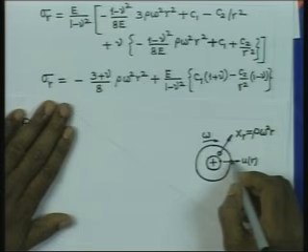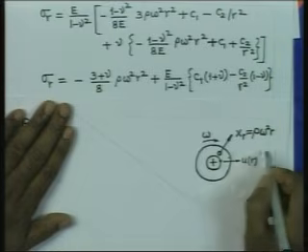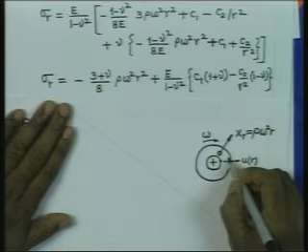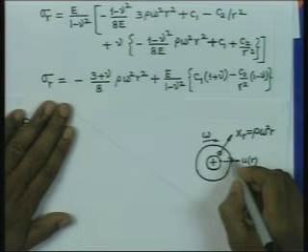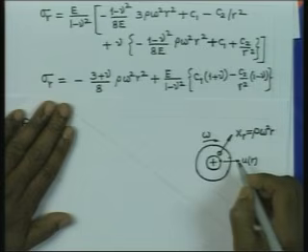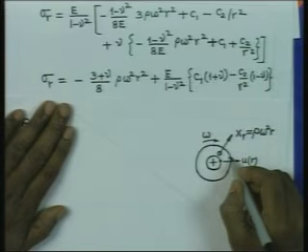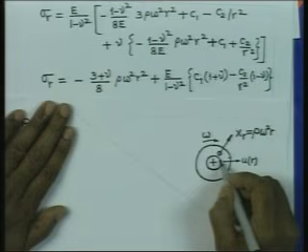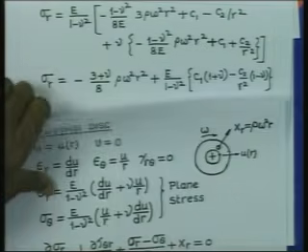Similarly, a material point which is lying slightly inside, the material layer which is to the right of it is trying to move away, and therefore, it will experience some radial force or radial stress, but for a material point which is right at the outer boundary, there is no material lying to the right of it. So, there is none to apply load in the radial direction, therefore, the radial stress on the outer surface will be 0. So, here at the inner surface radial stress is 0, so also at the outer surface it is 0.